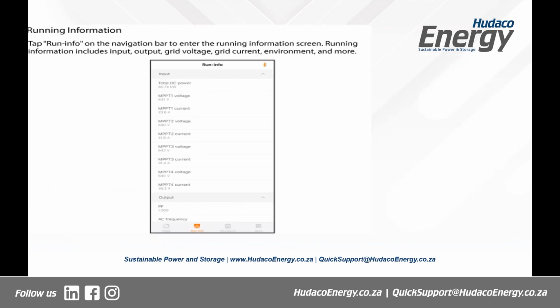If you click on run info in the navigation bar, which is this one below next to the home icon, you get the input, you get the output, you get the grid voltage, you get the grid current, and other aspects of the environment in which you are operating. Okay, so here, I think you can see it is showing us that MPPT1 has got 641 volts, MPPT1 current is 23.6, MPPT2 is this much, MPPT4 is that much. The reason for that is, let's say you have installed 5 strings and you're not getting what you're expecting.